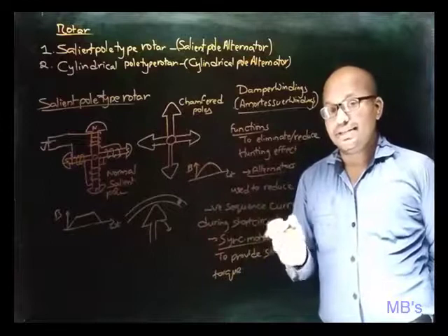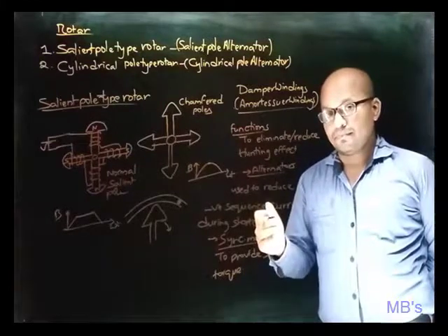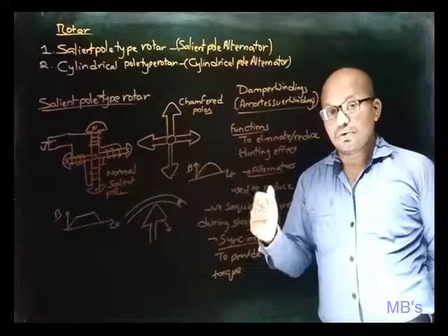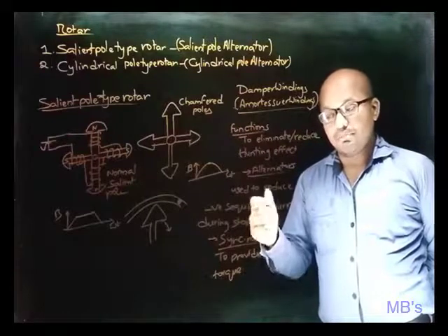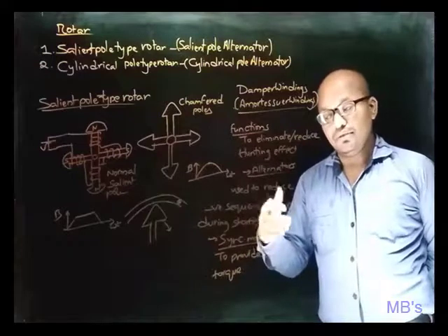So with damper windings, initially synchronous motors rotate like induction motors. Upon reaching close to the synchronous speed, because of magnetic locking, the motor achieves the synchronous speed and will continue to rotate at synchronous speed.